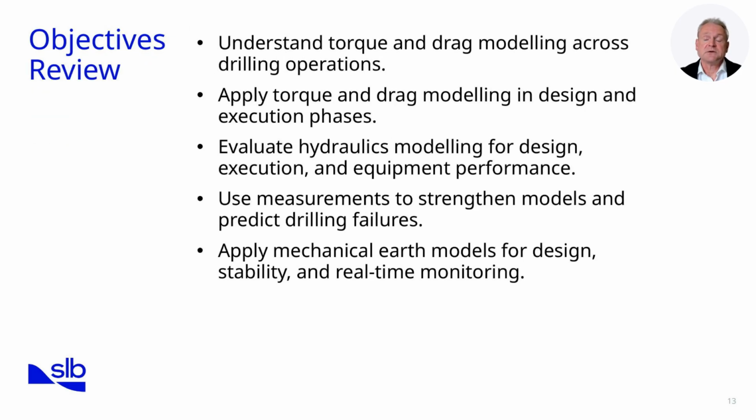Let's take a moment to review the objectives we set out at the beginning of this submodule and reflect on how we've addressed them. First, we aim to understand torque and drag modelling across drilling operations. We looked at scenarios such as rotating, sliding, tripping, and reaming, and discussed how torque and drag help us anticipate mechanical limits and wellbore conditions. Next, we focused on applying torque and drag modelling in the design and execution phases. We saw how modelling supports drill string design, trajectory planning, and rig equipment selection during planning, and how in execution it provides real-time indicators of hole cleaning, stability, and buckling.